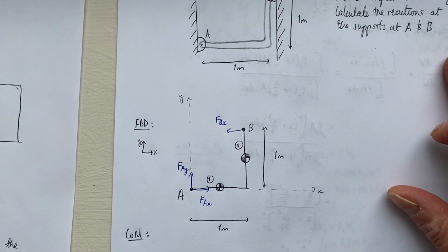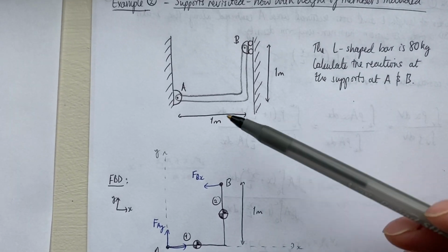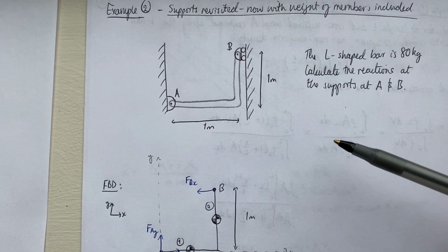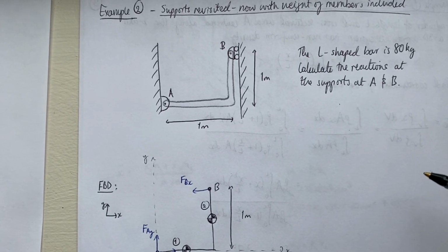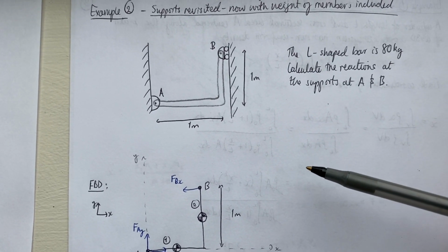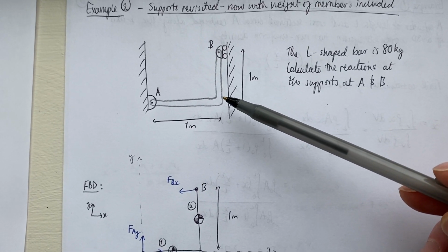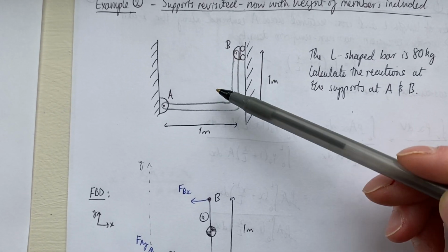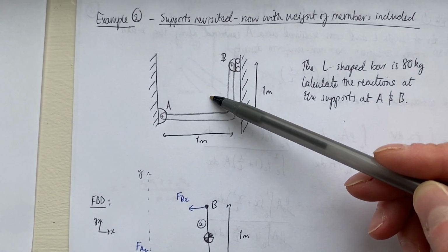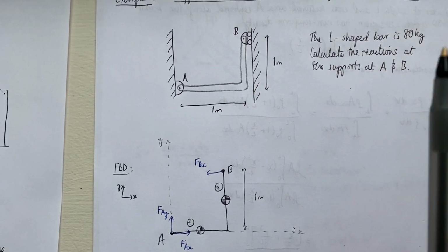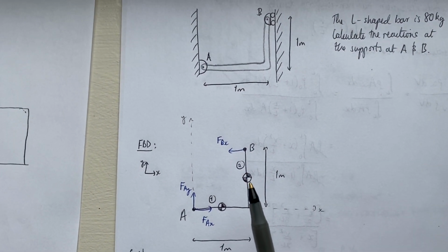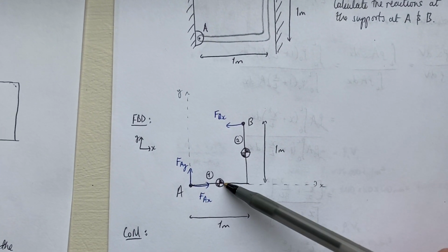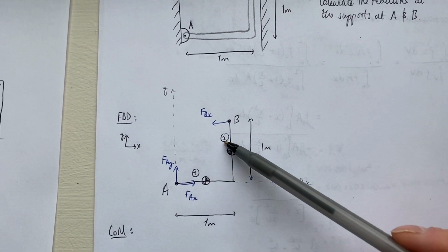So you'll remember when we discussed this before, that if we have a concave object, remember we talked about rings and curved lines, the center of mass isn't necessarily on the object itself, and that's what we've got here in this case, right? We're expecting the center of mass of this total object to be somewhere around in here, yeah? So let's break the problem up into two pieces so that we have this piece and this piece separately, and they have these two centers of mass, number 1 and number 2.